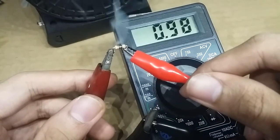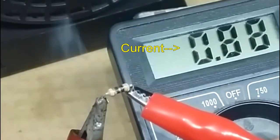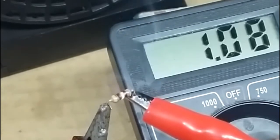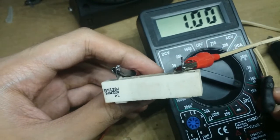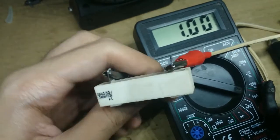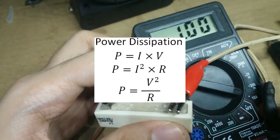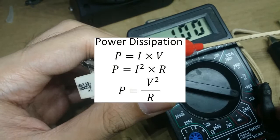This will happen when you overpower a resistor. This happens because the heat produced is too much for it to handle, so a high wattage resistor is needed. High wattage resistors are often big and can be mounted on a heatsink. Using these formulas, you can calculate the power dissipated on a resistor.